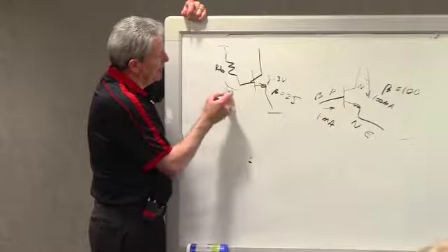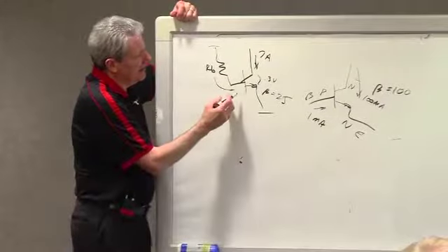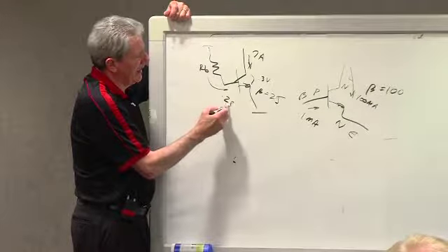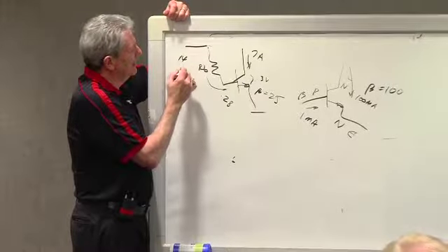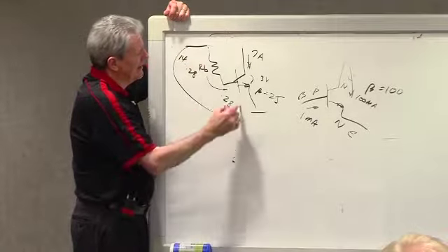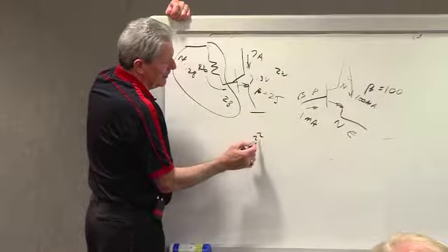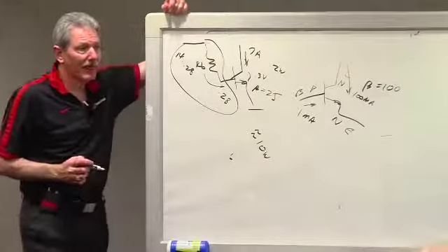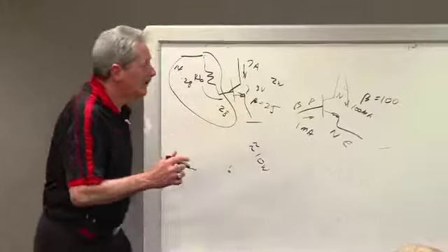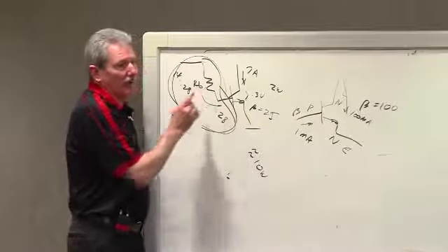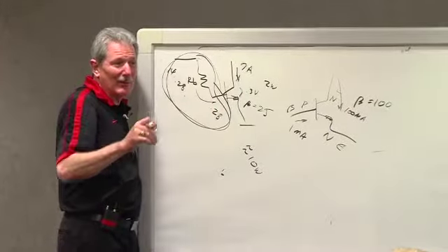So the amount of base current it takes, this is 7 amps. So that means I have to put 0.28 amps here. So if I've got 14 times 0.28, I've got 7 watts here and 2 watts here. So it's almost 10 watts. No voltage regulator that I know of has ever used a single transistor because of the bias power. This is 7 or 8 watts and 2 watts. Remember I told you got to keep it below like 5 watts?